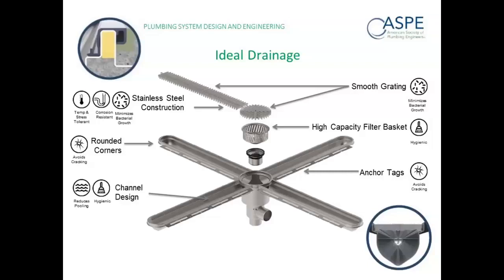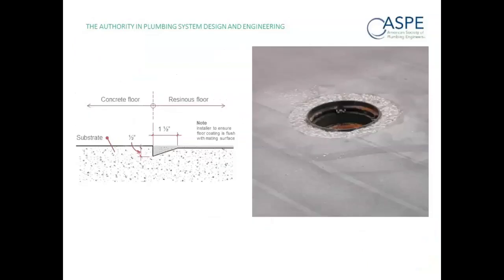And usually before our project engineer gets in the car, we already know the drain probably moved away from the floor, not the floor moving away from the drain. So I think having anchor tabs and having that void filled from the factory is critical to making sure you have longevity, whether it be in healthcare, food, any type of facility. Right, because that problem happens everywhere. It's not limited to these specific industries. Yeah, I would say it's the rule rather than the exception, unfortunately.